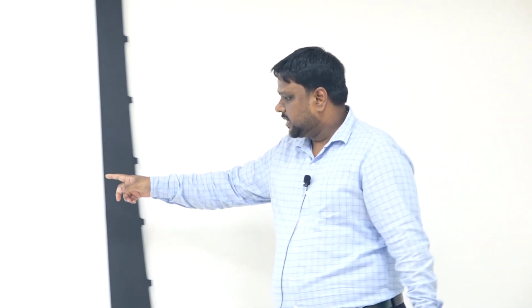Then you have another feedback gain, which is HV of S. So, now you have two control loops, you can see, right. One is the current control loop, one is the outer voltage control loop. So, you have to design first in such a way that the bandwidth of these two control loops don't clash. Okay. So, the thumb rule is basically you design the voltage control loop a bit slower and the current control loop also a bit faster.